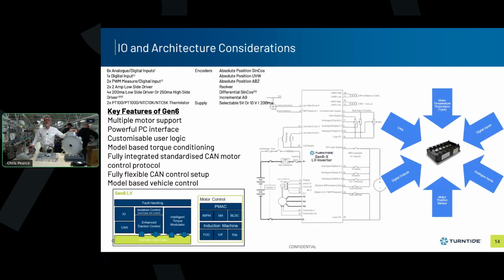Speed limits, torque limits, battery current limits, and voltage limits. So that's all available over the CAN bus. We can control the system according to a slave system, or we can set those parameters locally using a vehicle control system.